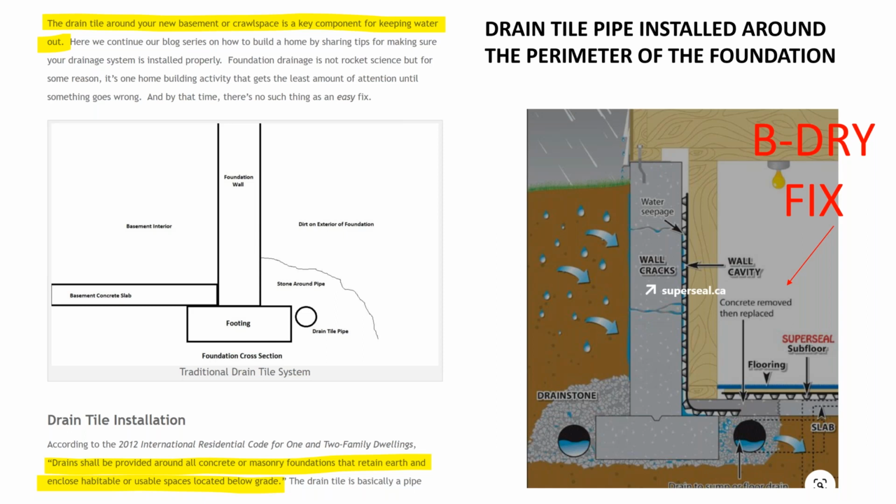And what happens is if the wall cracks, like in the photo to the right, they put a wall cavity, like a plastic sheathing, on the inside of the wall. The problem is that it still allows the water to go through the foundation wall, down in behind that plastic cavity into the drain tile, and then it flows over to the sump pump and it pumps it out.